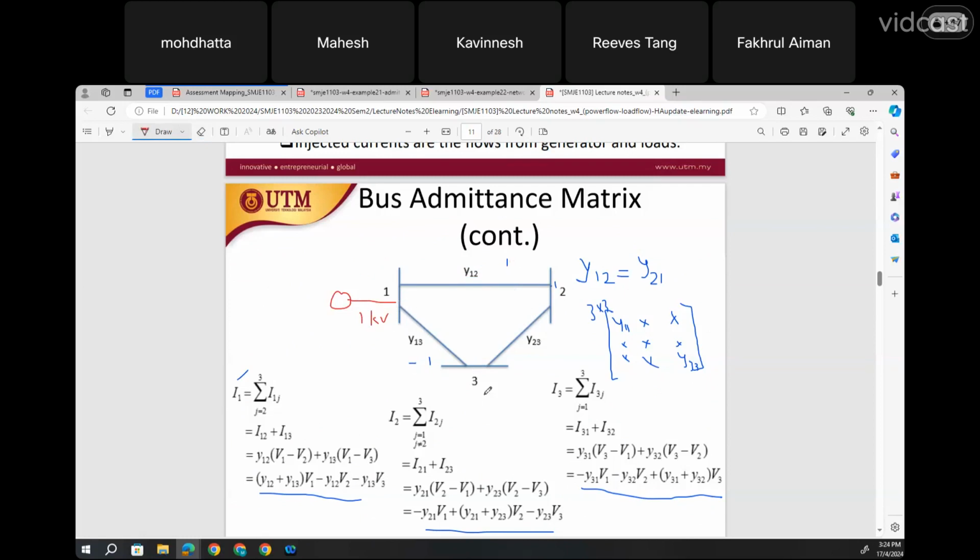We have a transformer and other equipment, and we see that this bus terminal, the voltage level at this part, will be 415 volts. And maybe here, with all the transformers, step down, step up, and so on, the voltage over here should be 240 volts. This is the ideal case in a power system. We expect that all the 240 volt equipment is connected here and the 415 volt equipment is connected here, so that they can function well according to the voltage level.